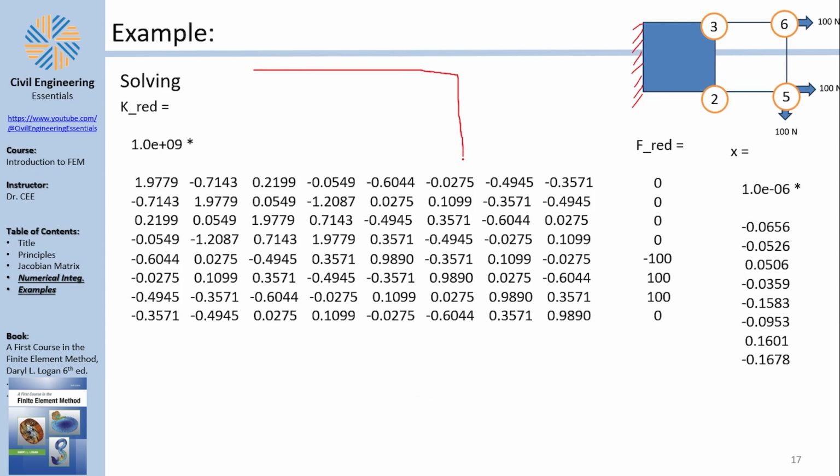This is the original plate in red. Let's take a look at the displacements that happened. So I'm going to exaggerate now. Those are not to scale. So let's take a look. Now for 1 and 4, nothing changed because those are pinned. Now this is the displacement of node number 2. You see a negative displacement in X, like this, and a negative displacement in Y, like this. So this is the new node number 2 after the displacement.